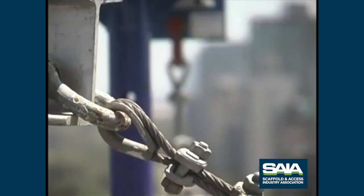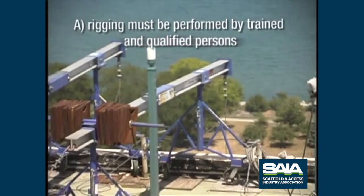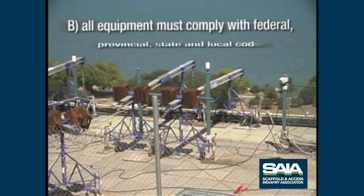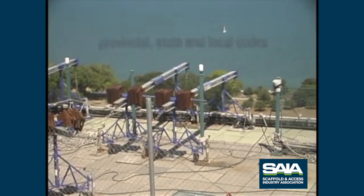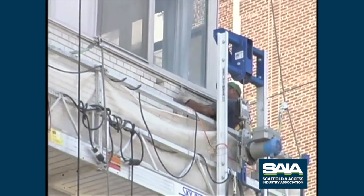The competent person must determine whether the equipment is in proper working order and rigged properly. A. Rigging must be performed by trained and qualified persons. B. All equipment must comply with federal, provincial, state, and local codes. The employer must instruct and supervise employees in the safe use of equipment and provide manufacturer's instructions.